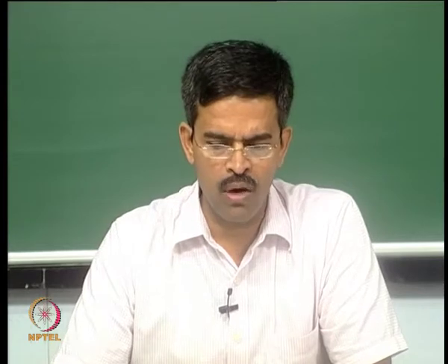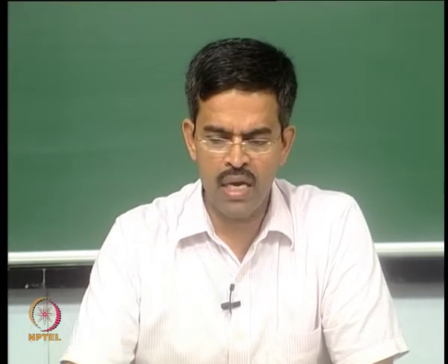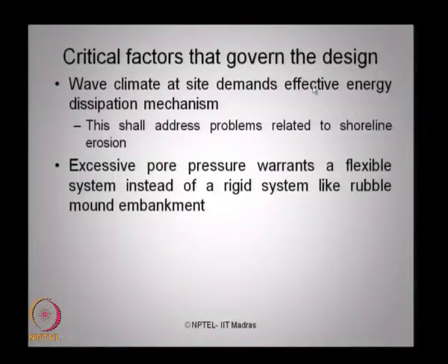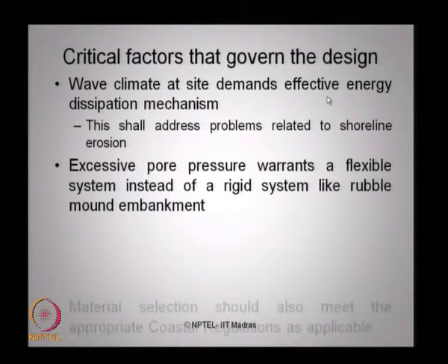So, I should look for a design which has an effective energy dissipation mechanism, as well as accommodates the excessive pore pressure located at the site. So, it should be a flexible system, and at the same time it should dissipate energy effectively.